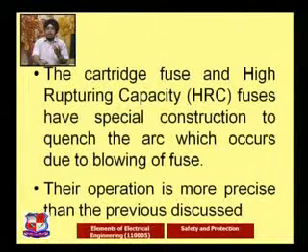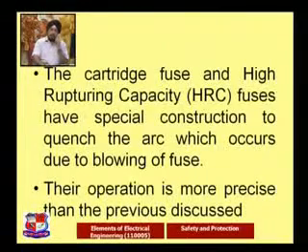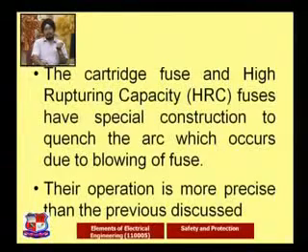The capacity or rating of the equipment or circuits is high, and that's why we have to deal with a higher amount of power or energy. So the fuse is going to capture that particular energy, and whatever arc is generated inside the fuse, it has to quench. So that type of medium is used in these particular fuses, which are the cartridge fuse or the HRC fuse.